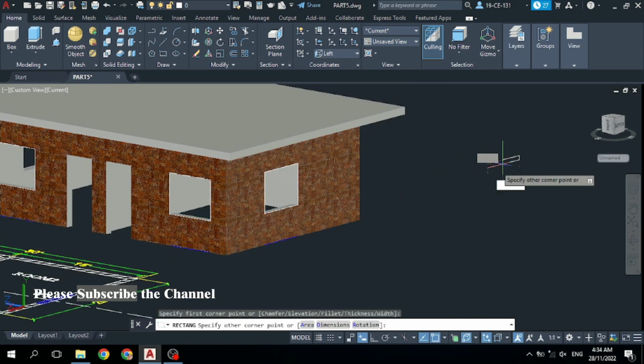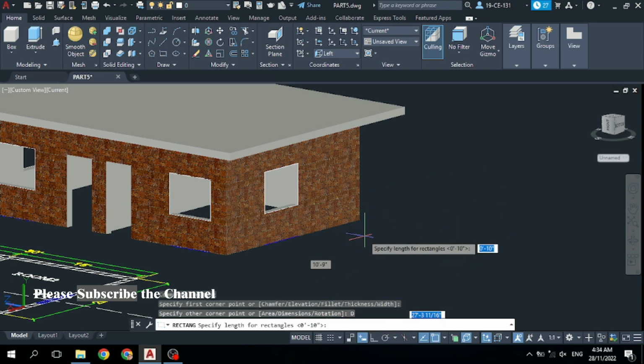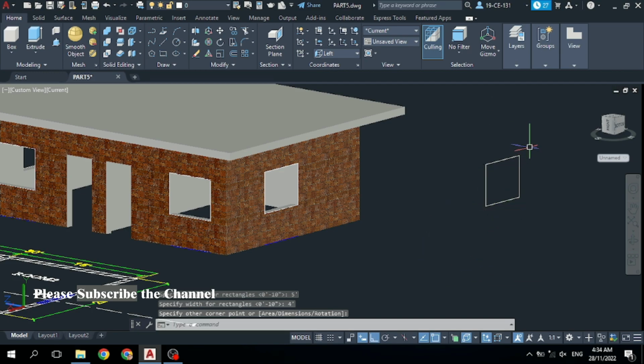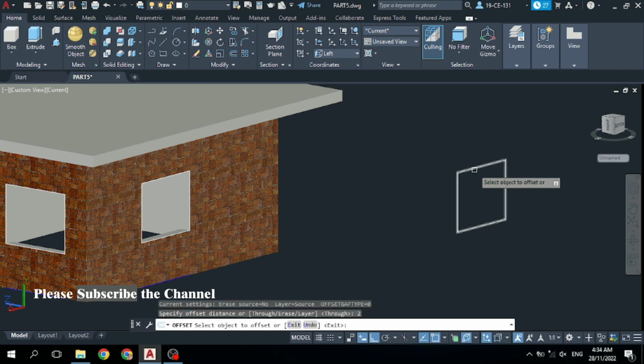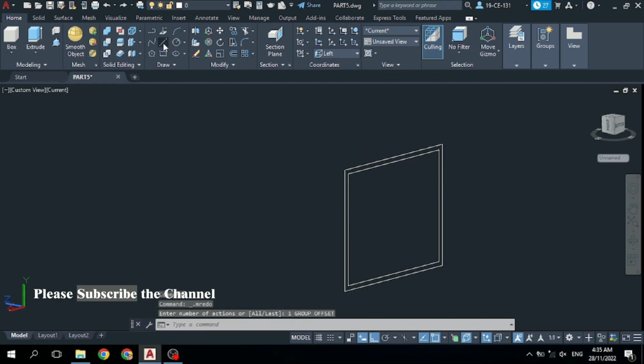is the length. So start the rectangle and click on dimension and type the length is 5 feet, press enter, and the height is 4 feet, and then press enter. Now you can see this rectangle is drawn, and after that click on offset. You can see this offset, and type offset distance 2 inches, and then press enter, and then select this object and then come inside. Now you can see it is offsetted by 2 inches, and after that take this line